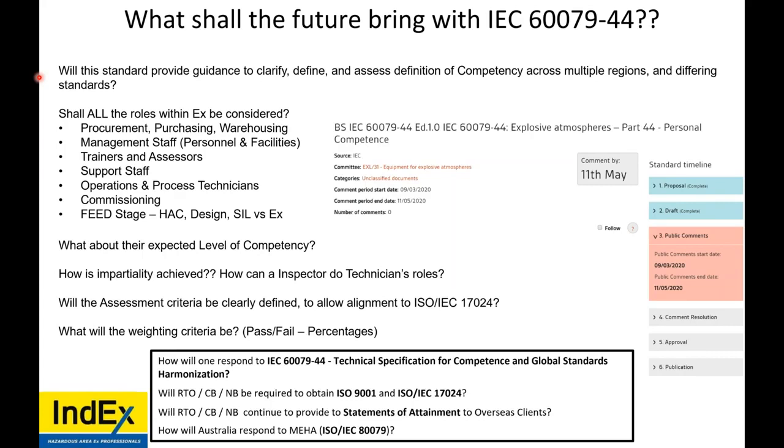So very happy with seeing that 36% for the hazardous area classification, because if the items are designed to an insufficient classification, that then spreads on to each and every other process along the way. It becomes difficult for the inspectors, installers, and during the operations of the facility, and the end user accepts all these responsibilities. If there are any existing issues, the end user receives them.